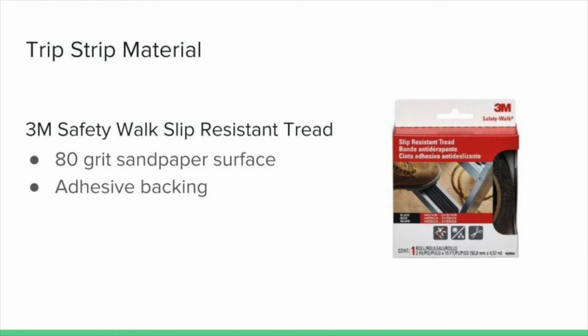For our mechanism to trip the boundary layer, 80 grit grip tape was chosen, traditionally used for anti-slip surfaces. It allowed for a sandpaper surface with an adhesive backing that allowed for easy and secure application. The consequence of using the grip tape was the highest roughness of the sandpaper available was 80 grit, and according to AERO, rougher sandpaper leads to a higher chance of full separation of the boundary layer.